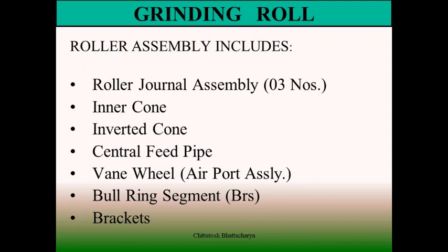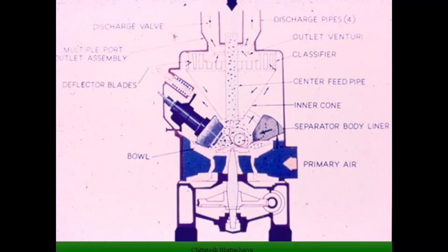Due to this vortex, heavier particles come down across the classifier bottom zone, and along with the coal feeding discharge line they fall into the bowl again for recirculation, and smaller particles move through the turret towards the pulverized coal carrier pipes, where there are butterfly valves to maintain the one-way flow of the coal air mixture out of the coal carrier pipes.